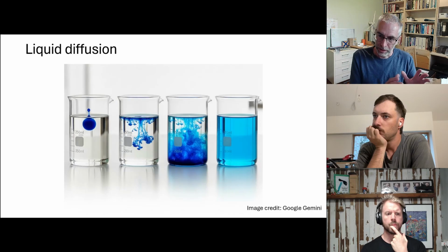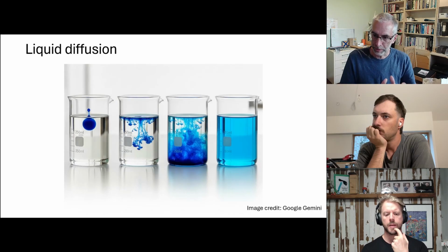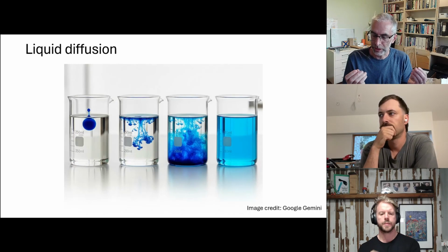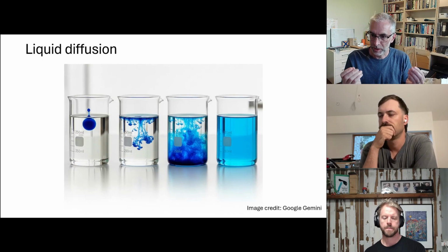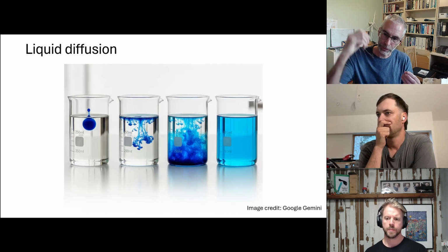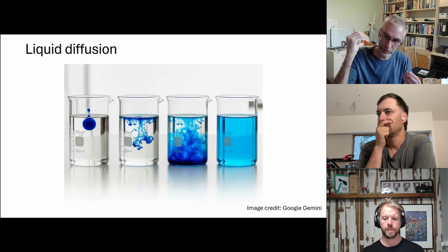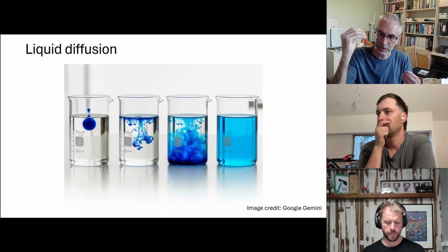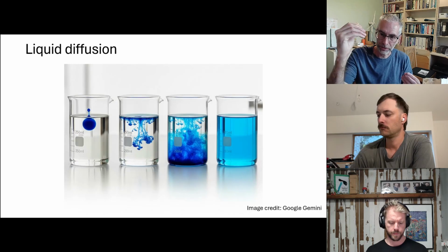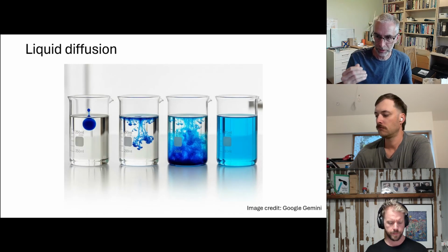All right, let's go now to the more complicated part of the problem, which is the water vapour. So these are the molecules of water that are floating in the air around us all the time that, potentially in a heating-dominated climate in the winter, will tend to diffuse or make their way out through our wall or up through our roof, and they will then reach our substrate, be it ply or OSB, and they're trying to drive their way out and through. And so the critical thing here, of course, is we're trying to make sure that we allow those water vapour molecules to draw out through the assembly and not accumulate on the underside of that substrate.